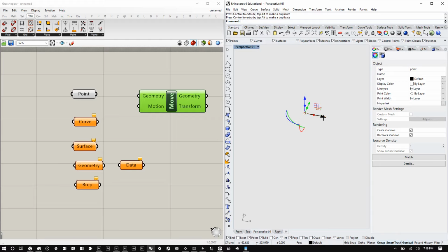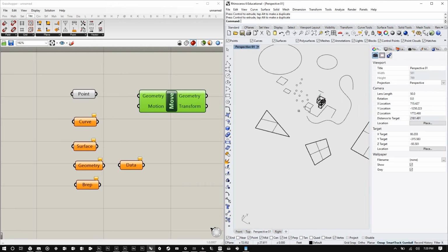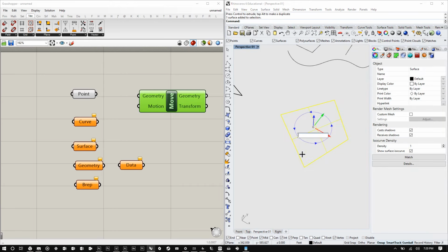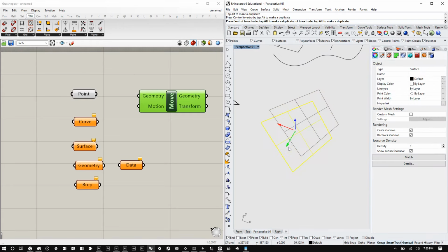You'll also see some rotation commands. In this case, it's a point, so its orientation doesn't matter, but these bars right here allow you to edit its rotation. So if I go over to an object that actually matters that you rotate, let's say this one, and I want this to be rotated 180 degrees, I can type in 180 and hit enter, and now that object's been rotated, or I can just grab it and rotate it manually. So gumball is fun for flexible modification. If you want to do something that's accurate or exact, I would type in the command, so the rotate command or move command. That way you can have more control over what you're editing, but if you're just moving things freely, the gumball is a great way to do that.